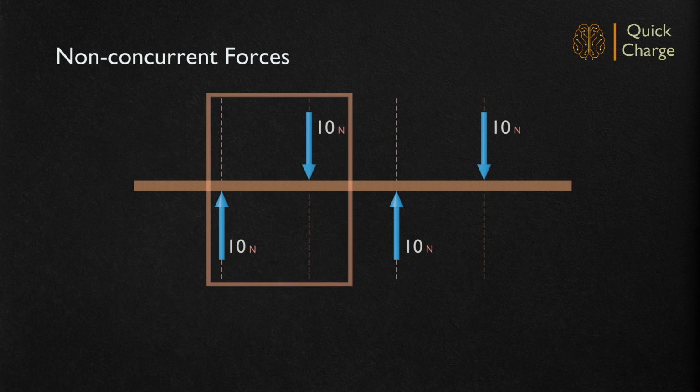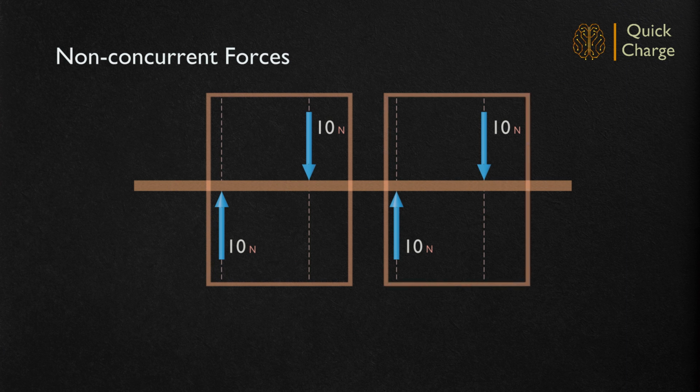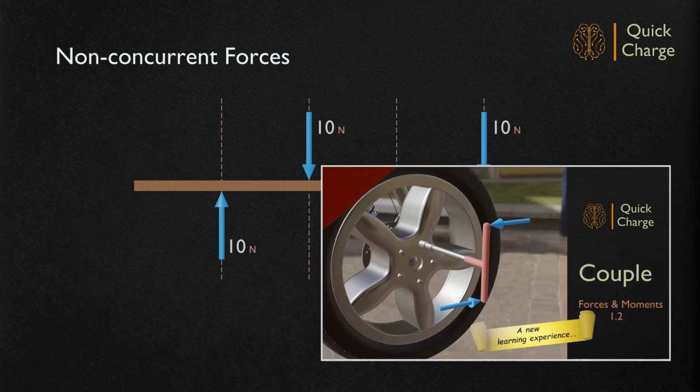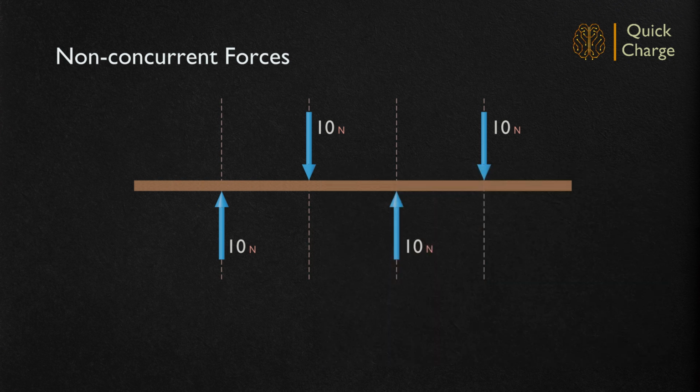We can see that two force couples having same magnitude and direction are acting on the system. The moment of couple initiates a rotational effect and the system will not be in equilibrium. Detailed information on couple and its impact on the system are covered in a separate video. Let us evaluate the moment of forces about an assumed location, say the edge O of the beam.